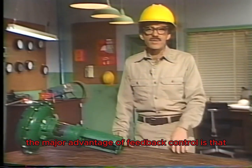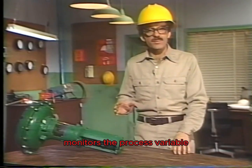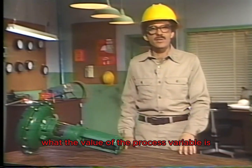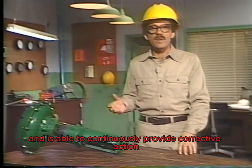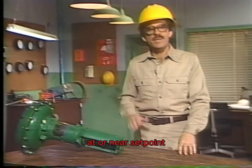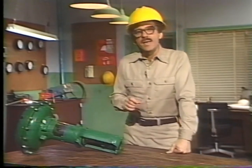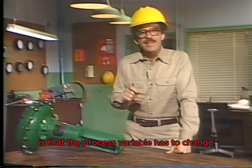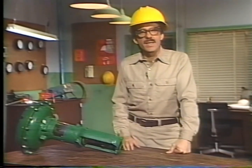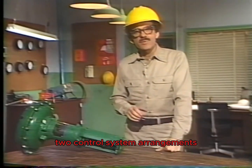The major advantage of feedback control is that since the control system continuously monitors the process variable, it always knows what the value of the process variable is and is able to continuously provide corrective action that maintains the process variable at or near set point. The major disadvantage of feedback control is that the process variable has to change before the control system responds to correct it. Now, you may recall that I said we'd look at two control system arrangements.